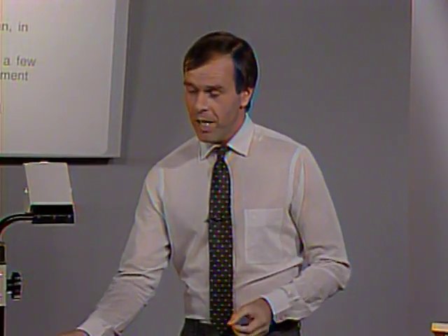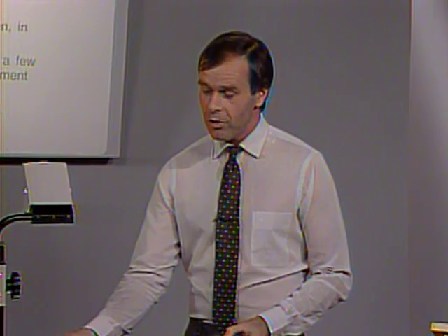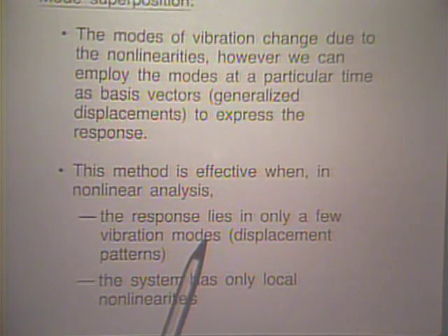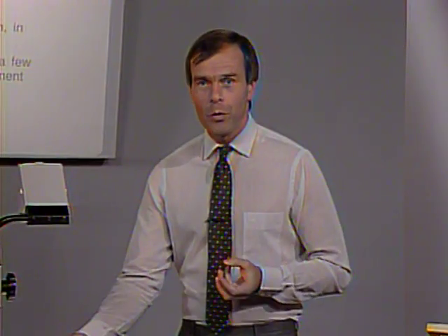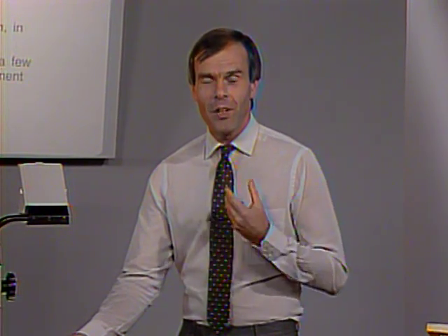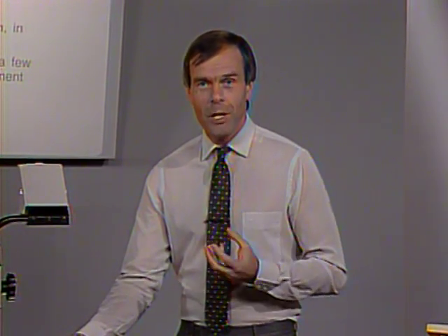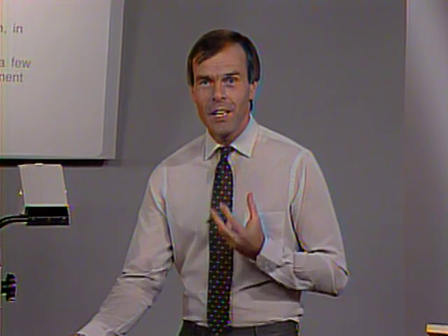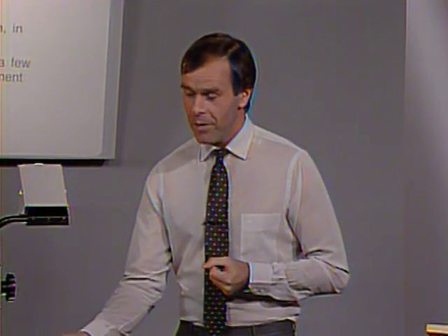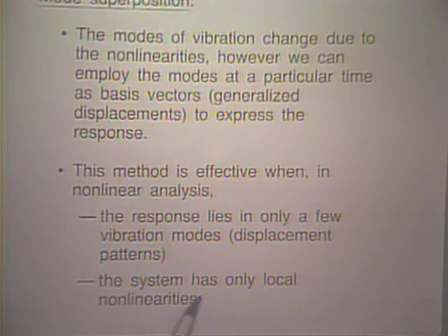The method is effective when in nonlinear analysis the response lies in only a few vibration modes, just the same way as we are applying mode superposition also in linear analysis, namely it's only effective really when a few vibration modes capture the total dynamic response. The same holds here, of course, in nonlinear analysis, and when the system has possibly only local nonlinearities.